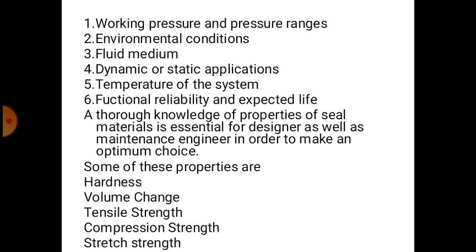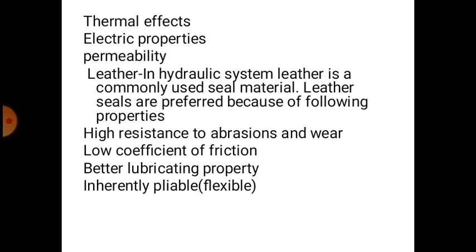A thorough knowledge of the properties of seal materials is essential for the designer as well as the maintenance engineer in order to make an optimum choice. Some of these properties are hardness, volume change, tensile strength, compression strength, stretch strength, thermal effects, electric properties, permeability.